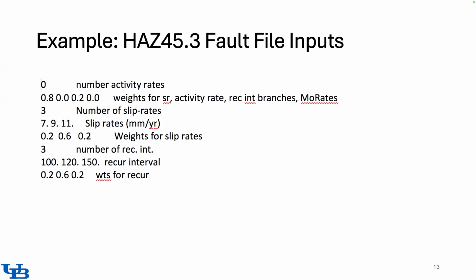So this will be if you have done some trenching and you were able to go through essentially, I don't know, 300 years of ruptures, but you are not really sure if it's 300 years, and you have a mean recurrence interval of 100 years, or only two of the scarps that you see are actually associated with tectonic faults, and that there is something else, or some alternative interpretation of the data that you have.